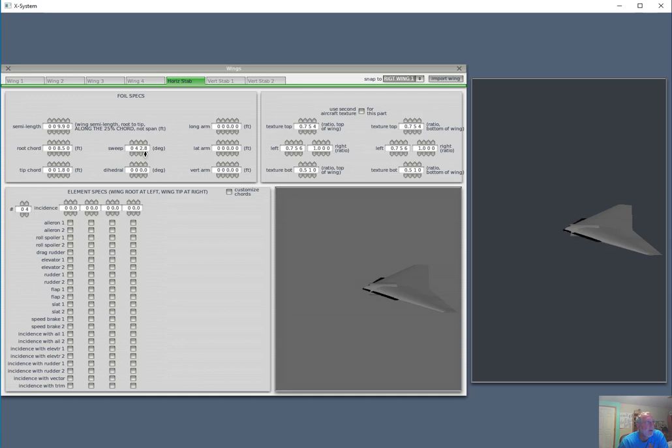So there's our horizontal tail, got the sweep, and we need to put the longitudinal arm. We need to move this back to where it belongs after the wing. We've got 32.13, and we're going to move this up 3.7 into the correct position vertically.